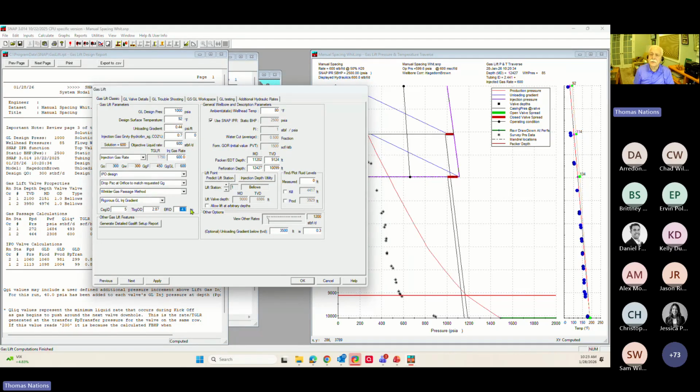It actually uses the complex hydraulics from whatever method you choose, and it calculates the hydraulics based on friction on both of the wetted surfaces, that's the OD of the tubing and the ID of the casing. Those 2 wetted surfaces and the friction of the fluid flowing up there is the way you should calculate that, and that's the way SNAP is doing it. But just FYI, if you wanted to guess what the equivalent diameter would roughly be. All right, so that's some of the input information I need over there.